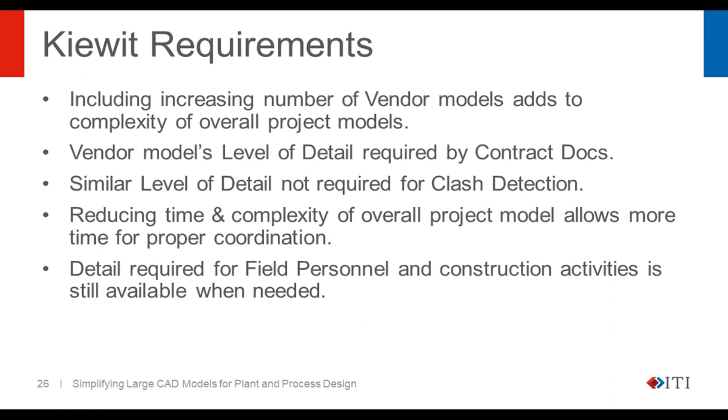A big part of that is that level of detail in our clash detection process is really not needed. So like Andy mentioned, the nuts and bolts and holes and some of the interior parts to the larger structures aren't really needed when we're doing clash detection. So simplifying those models really helps out a lot. By doing so, this reduces the time and complexity of the overall project model, and I'll get into more detail about our testing that we did for using CADfix on a lot of this stuff.